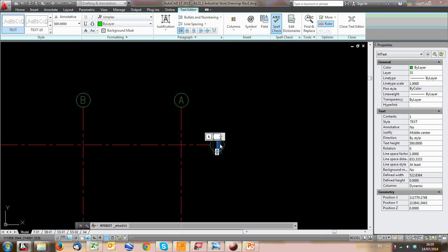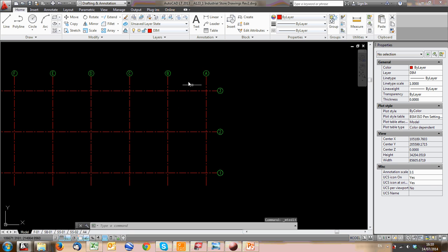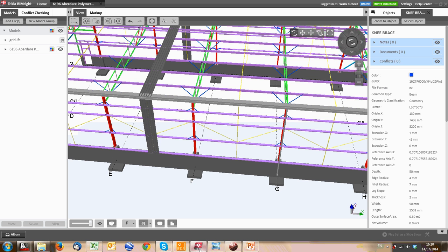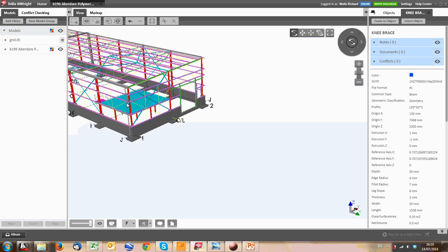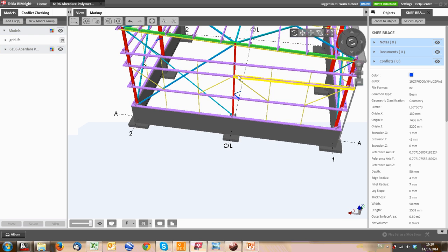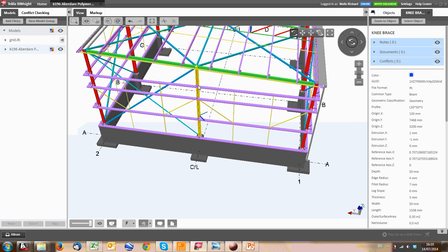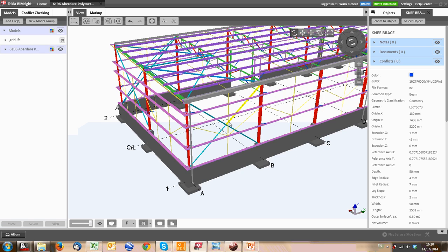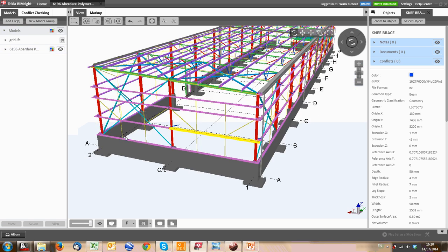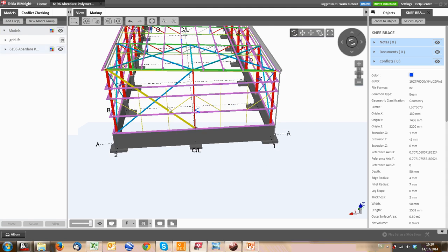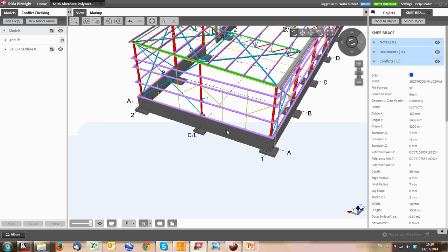The reason I used two bays in this, because each of these, the space between a grid line is a bay normally. So the reason I did that is because on this gable face, the gable face is this sort of face here and here, I wanted one column in the middle. So that was where the 7.5 came from. I could have gone with a 5-meter bay. It was actually just easier because then this span is the same as this span, so it just made the girts the same all the way around, so it just was simpler, and also less bracing and less other things here. So that's why that 7.5 dimension came in.